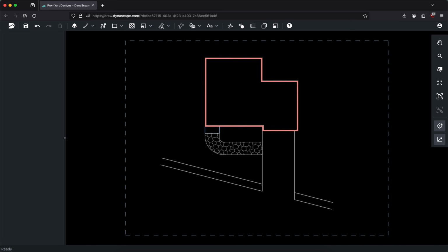As a side note, the reason I'm being careful about the layers I use in each tool is that our layer system is designed to include preset line weight. And proper line weights make the design easier to understand by adding depth and character to the drawing, which helps to visually communicate the dimensionality of the space. Typically things like hatch patterns are represented by thin lines, and thicker lines are used for more prominent objects like buildings, structures, and trees. So when I'm taking advantage of Creator's layers, that just means I don't need to modify the line weights for each individual entity or hatch I'm making.